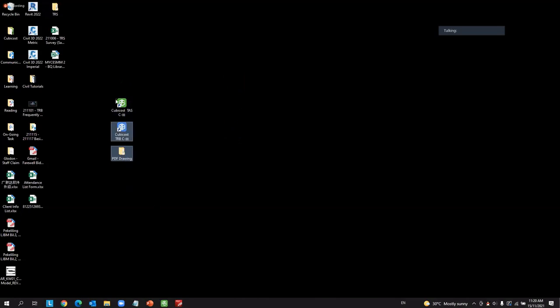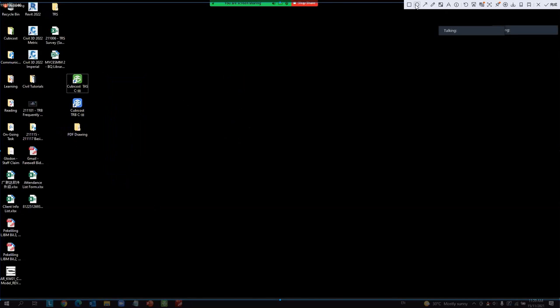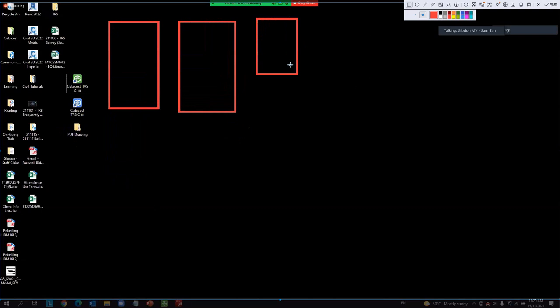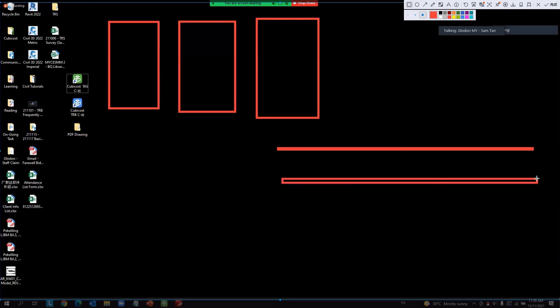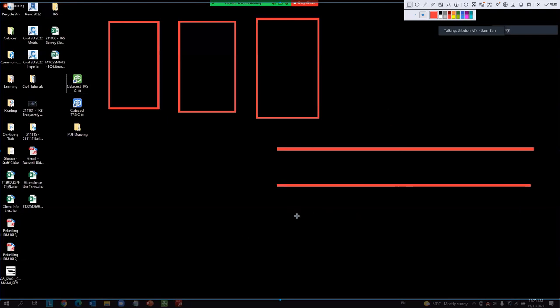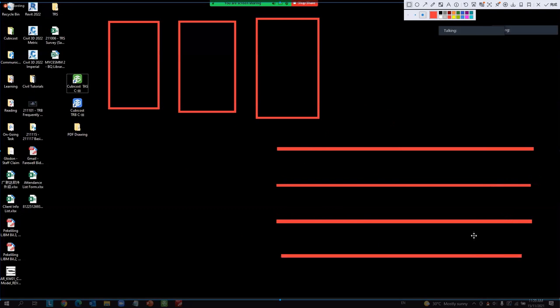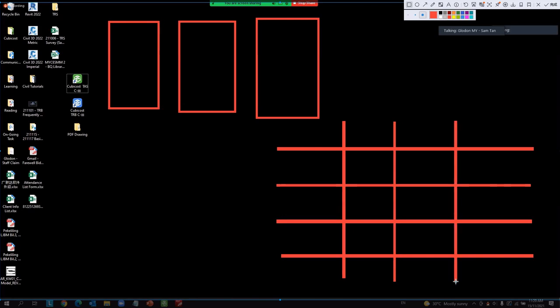Currently I have my ground floor plan, a separate plan. I have my first floor, later I have my roof floor. I have all the floors here, but my drawing panel is actually at a random point. Any location can be used. So I will need to determine my XY direction, my axis grid line. My axis grid line needs to follow strictly from the structural drawing or architecture drawing, whichever takes precedence. So I will have this grid line.